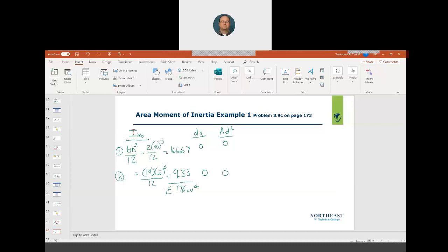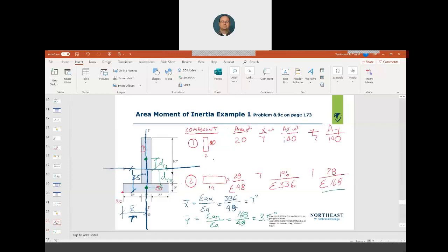So this is the parallel axis theorem. Is there a centroid that is not on the composite centroid, an individual component centroid? If I look at my diagram, there is not. The individual component centroid is 1 inch in here, and we got 7 here. So I go 6 plus 1, it falls right on there.